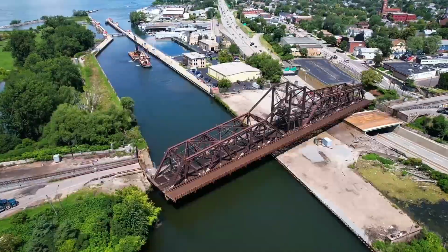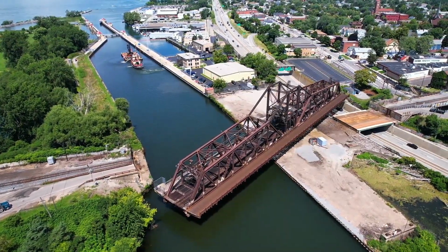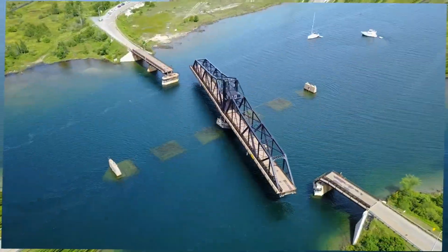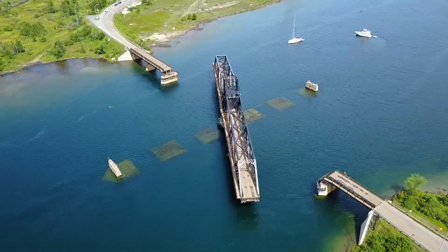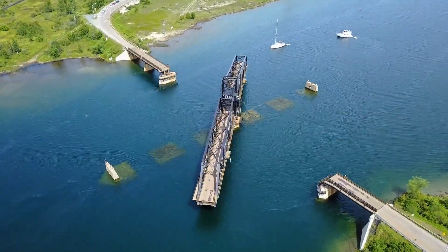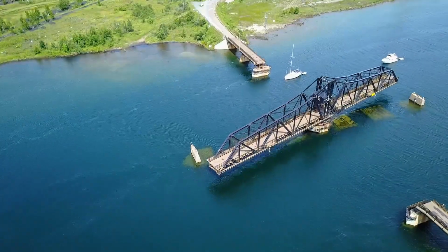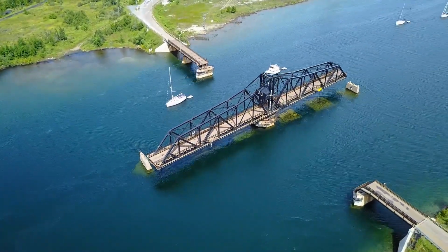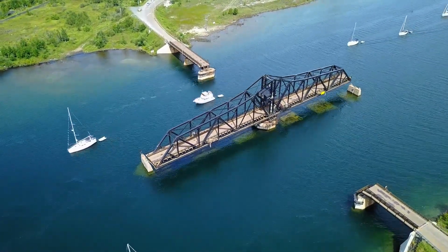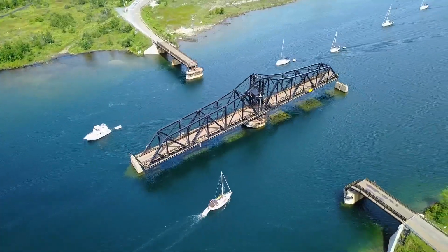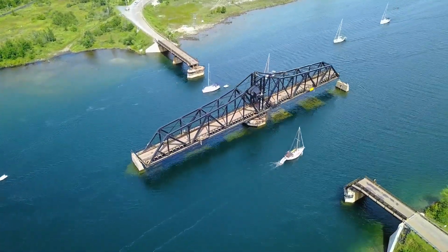Swing bridge. A swing bridge rotates horizontally around a central pivot point, swinging open to allow vessels to pass on either side. They are commonly used over rivers and canals where the span is too long for a simple lift or bascule system. Swing bridges require space on both sides of the pivot for the rotating deck, but are durable and effective for moderate ship traffic.